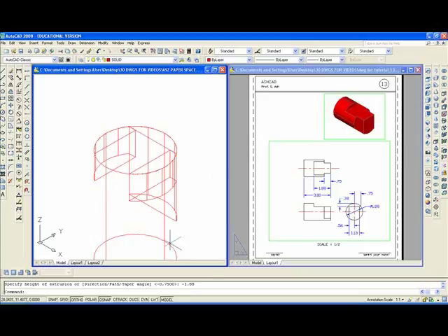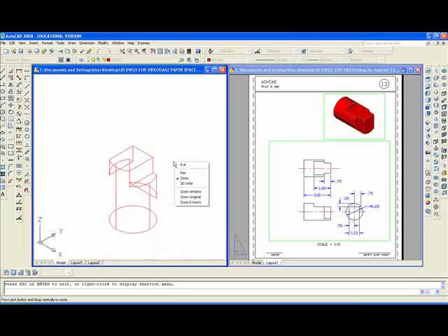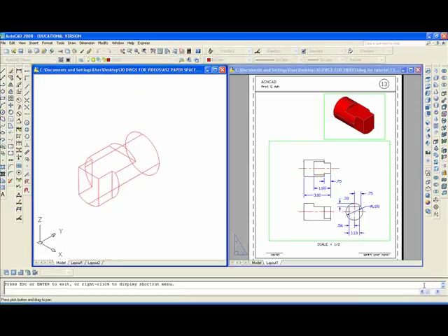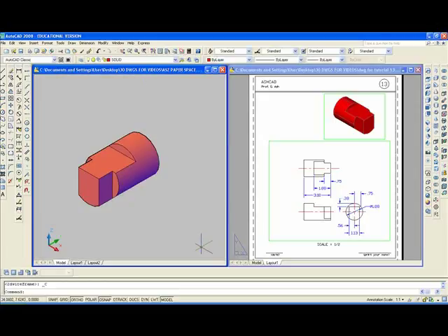Now I think you'll want to subtract. So we're going to go here to subtract from the big cylinder, that segment, and that segment, enter. I'm going to use zoom real time. Doesn't look right, it looks weird. Well, anyway, I'm going to 3D rotate that. Pick a base point here at the center of that, right there like that. Red one, and we'll type 90 and pan upward. Give it some shading. It does look right, but it's in the wrong direction.